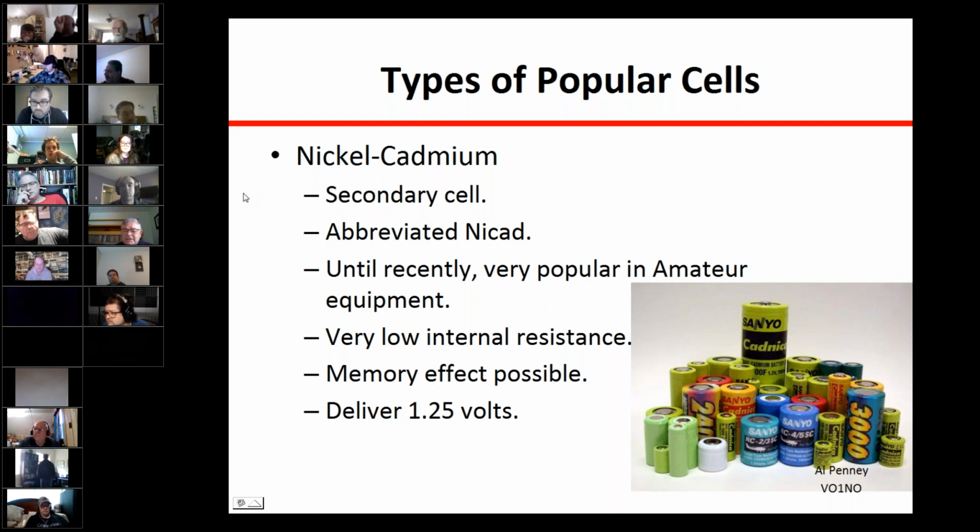Claude, batteries generally don't create noise for a radio system. They're very quiet electrically. And as Diesel said, yes, they operate best at room temperature. For storage, you might want to keep them cool, but they're best at warmed up. You certainly don't want to use them when it's cold outside. Most batteries will lose capacity when it's cold because it's a chemical reaction. And in general, if you cool off a chemical reaction, it doesn't react as well.